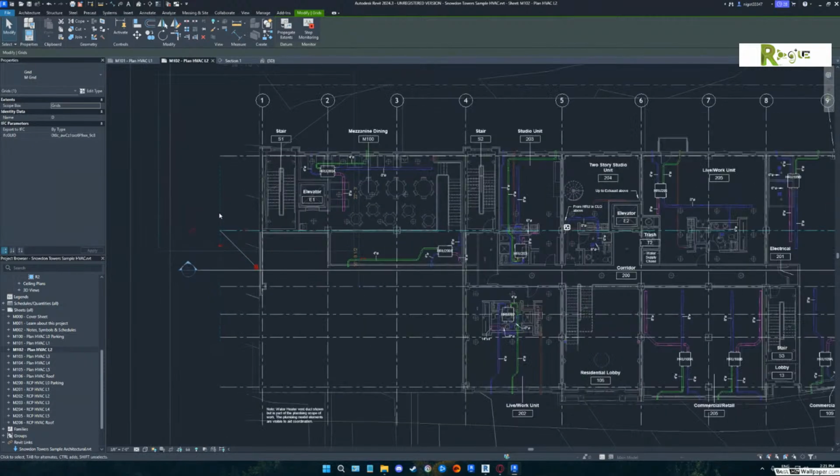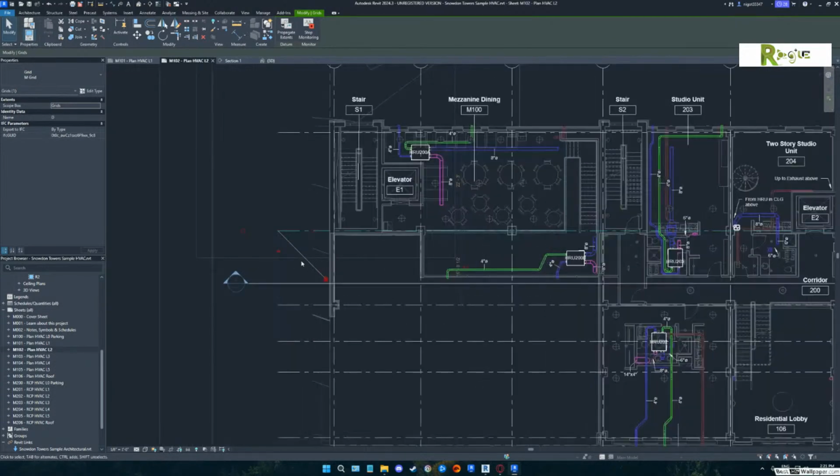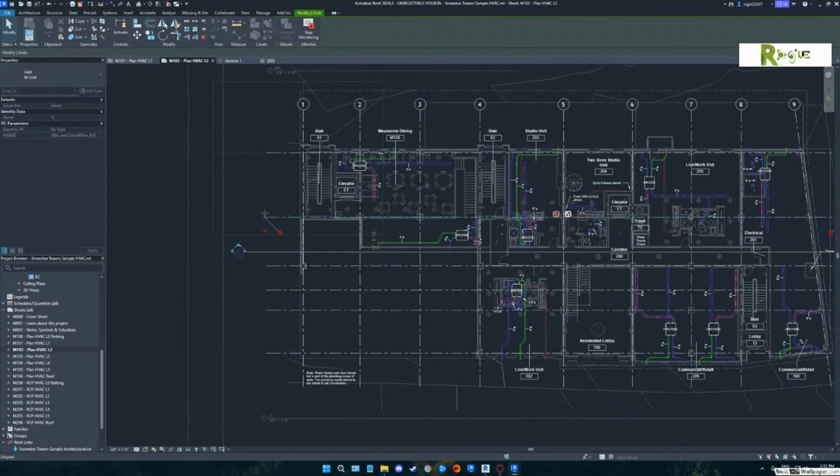Oh, I see. Why is this? You can't see the scope box that it's locked to. It shows up when you're seeing it, but if you look in your properties, the first thing in the properties says scope box grids. Make that say none. See, now you could stretch those column grids. Only the one you've got.